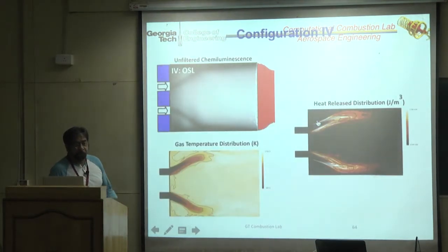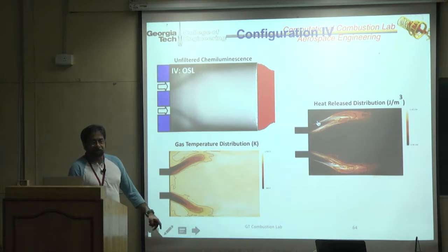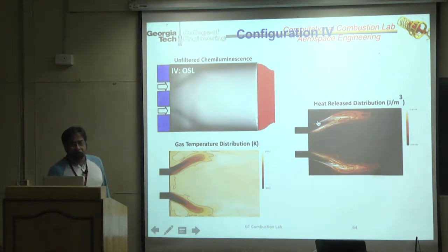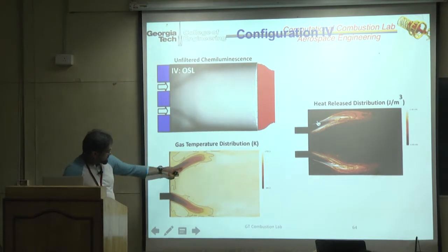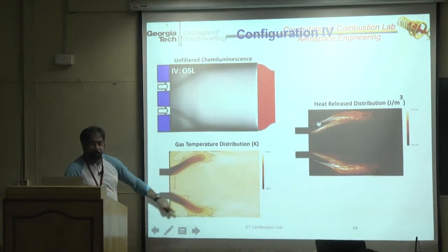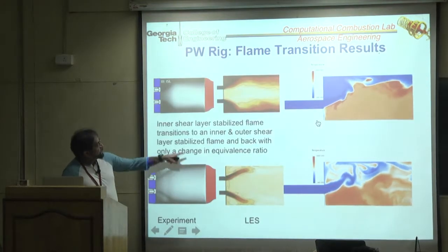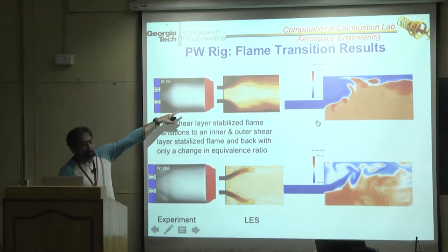I have no idea. I mean, they were running commercial codes, right? Like Fluent. They were running the same problem. We gave them the same grid and same boundary conditions. We even gave them our restart solution. But every time they ran it, it went back to this flame. This flame is very easy to get because there's a recirculation here. Almost any code will give you that. But it is very difficult to get that kind of flame.